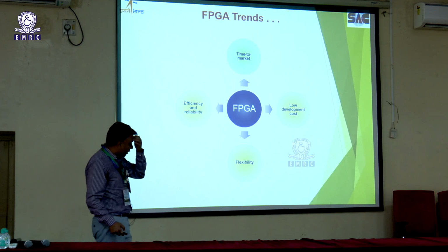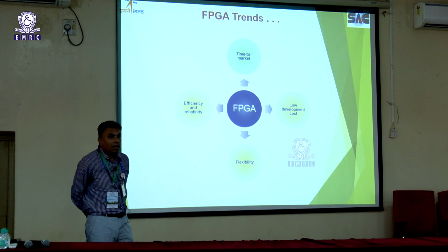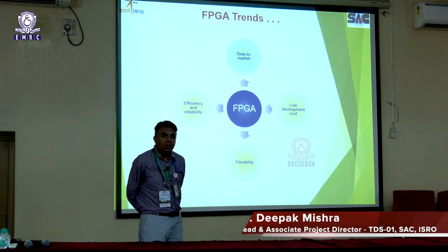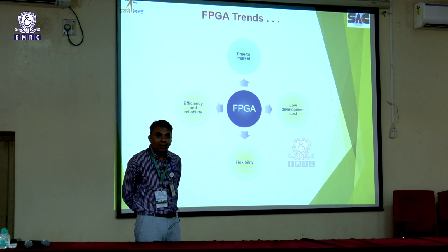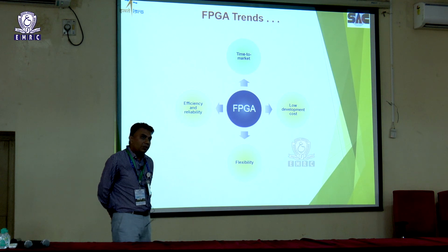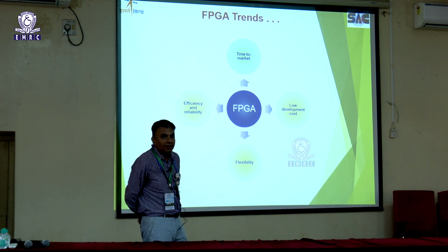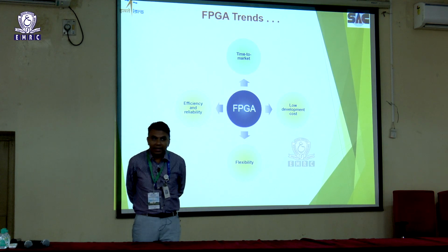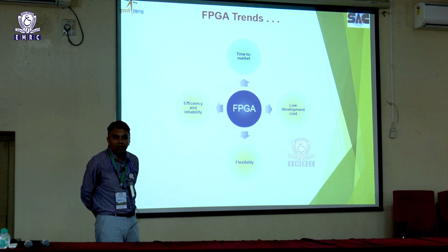As you see the trend of current FPGA based designs, basically they are market driven. You can see that initial FPGAs were 180 nanometers. Nowadays, whatever I am talking about is for space qualified FPGAs. Currently, the space qualified FPGAs are 28 nanometers, and the latest devices are like RTG4 from Microsemi, Virtex 5 from Xilinx, and now RT PolarFire.